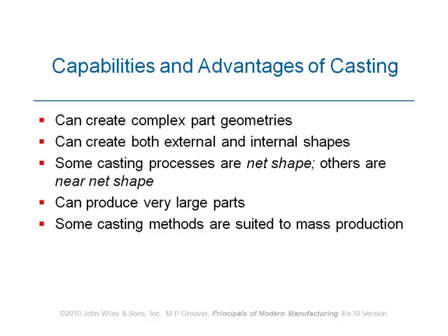One of the most important methods which is used as a complementary process on casting processes is machining. So you may see it very often in industry that a part is initially produced by making use of the casting process, and eventually it is subjected to another process or a number of processes such as machining, coating, etc., in order to enhance its properties and to improve its dimensional accuracy.